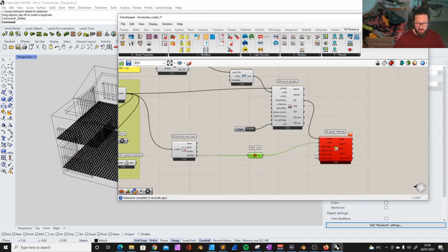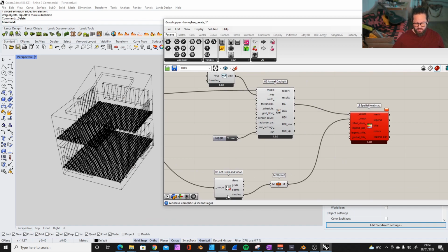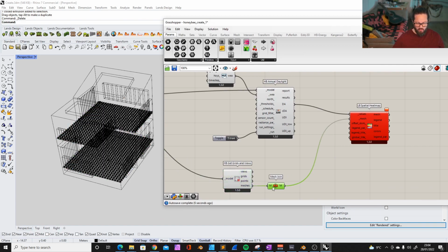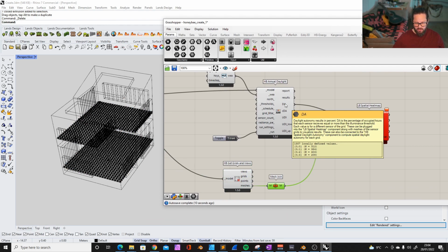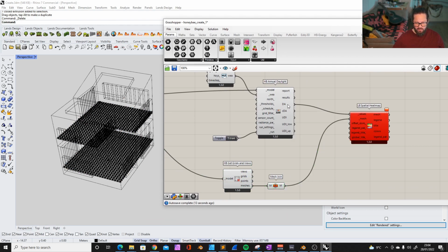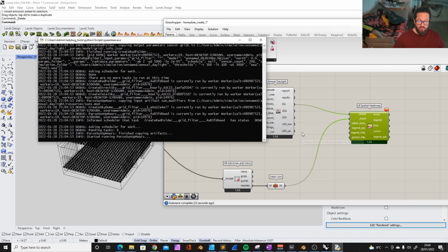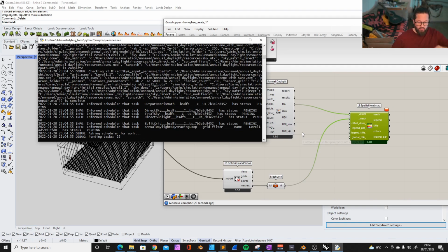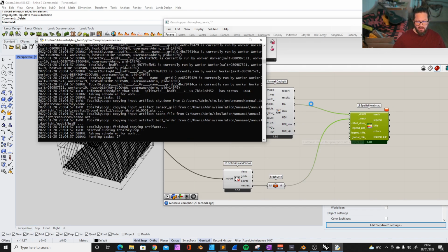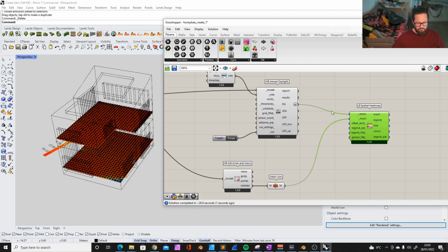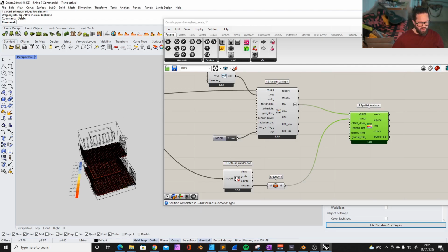It still doesn't work because now we have one mesh, but we have 3 lists of values, so we need to flatten that list, so then we have all the values together. There are other ways to do that. We can select by room, and we can look at that next time. Yeah, see, it worked.